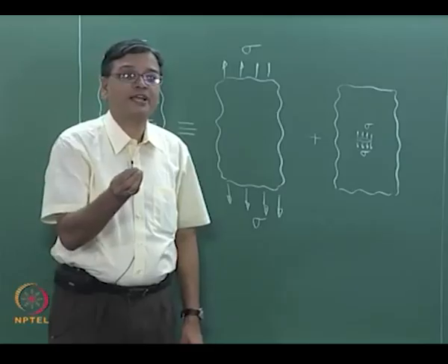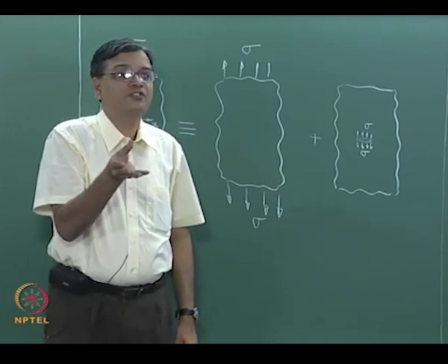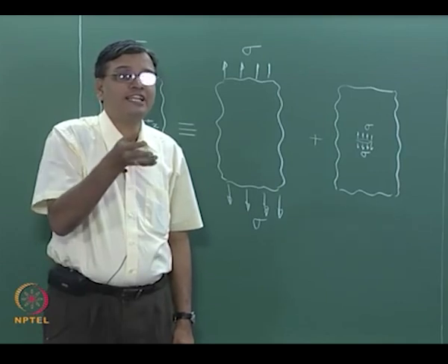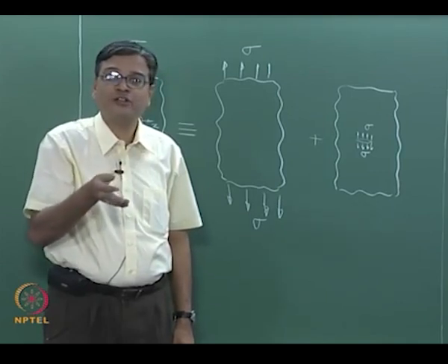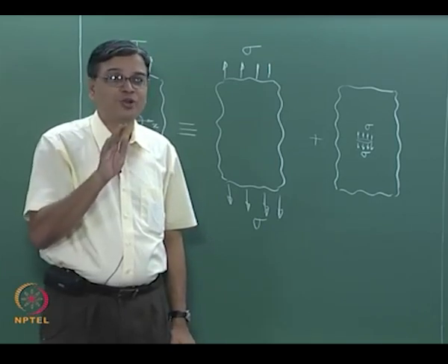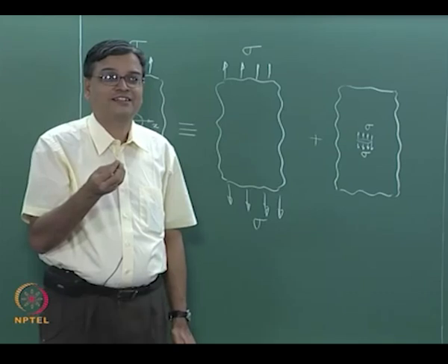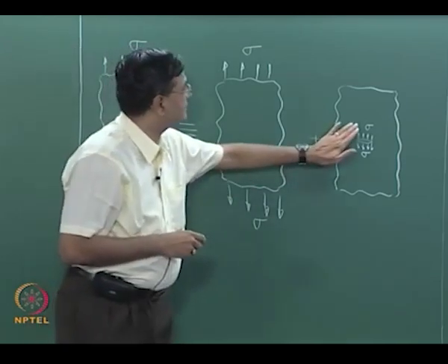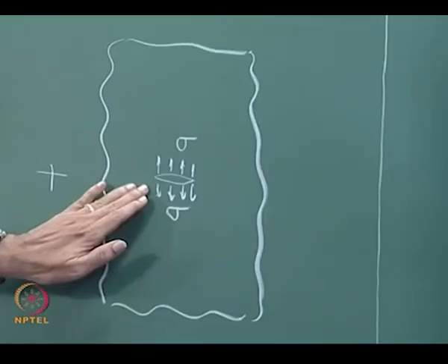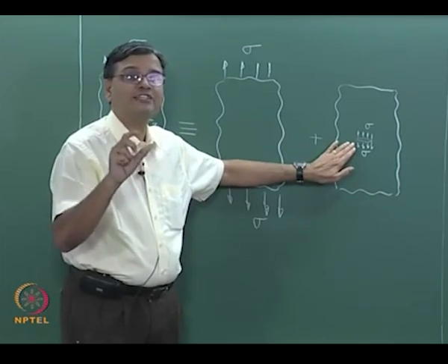It is like you supply an internal pressure and then the crack opens up. So, from the energy release point of view, whatever the work done I do to open it is the energy that is required for me to form the two new surfaces. See, mind you, this is a thought experiment, you will have to visualize this mentally. Now, with this information, when I have sigma, when I have the displacement V, which is already determined from crack opening displacement, can you write the expression for energy?